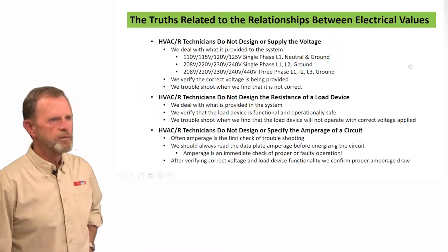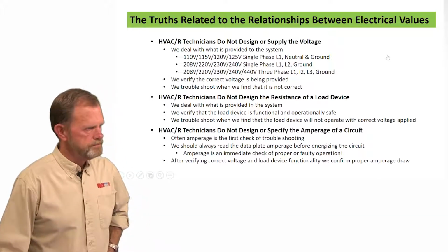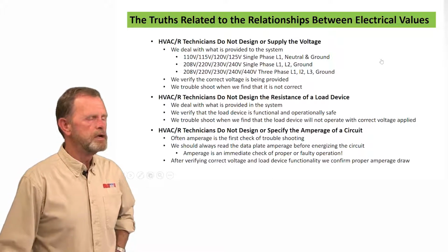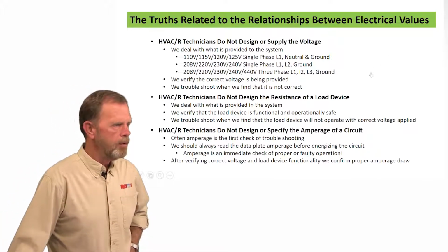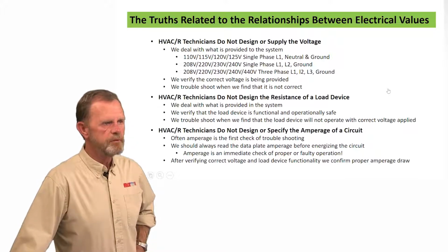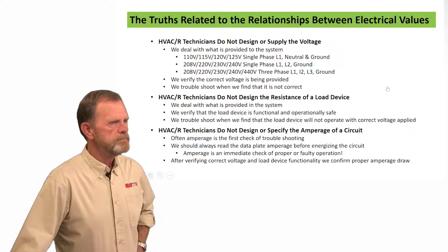110 to 125 volt single phase. It's L1, neutral and ground, or 208 to 240 volt single phase. That's L1, L2, and ground. Or in the three-phase market, 208 to 440 volt three-phase, L1, L2, L3, and ground.